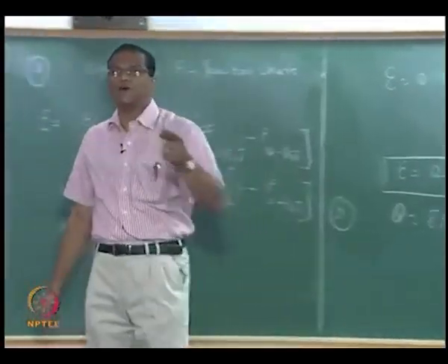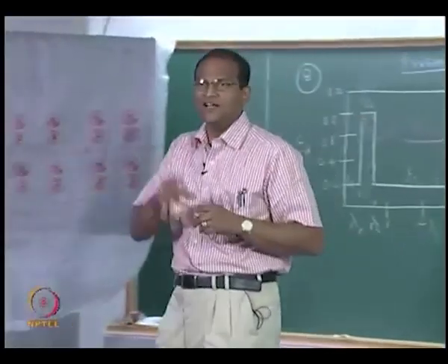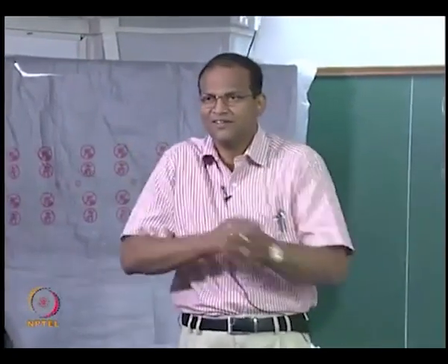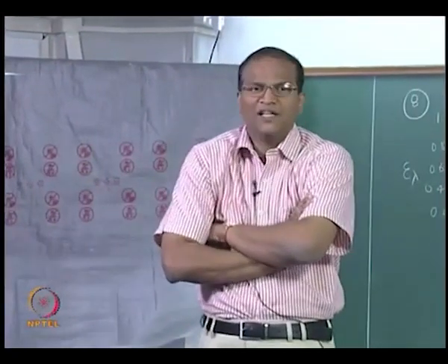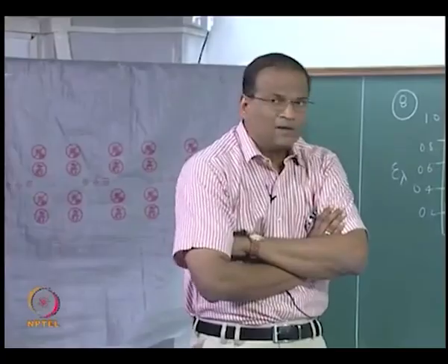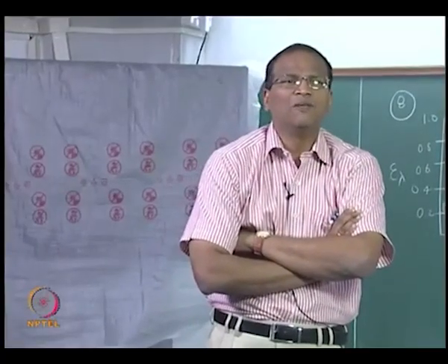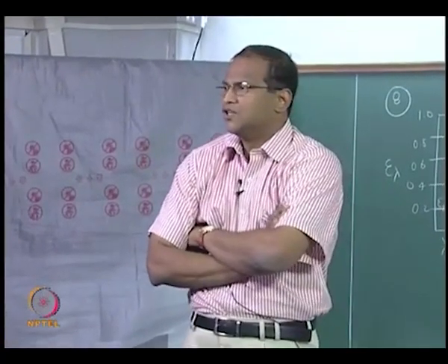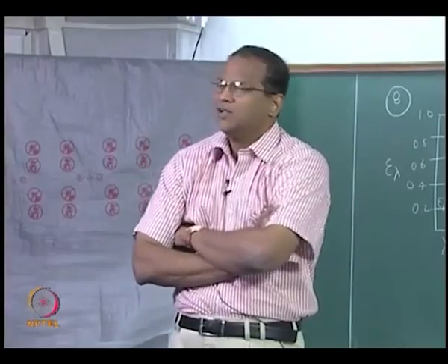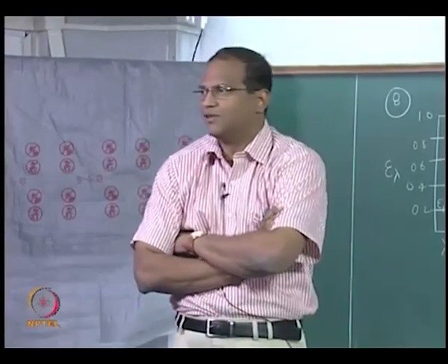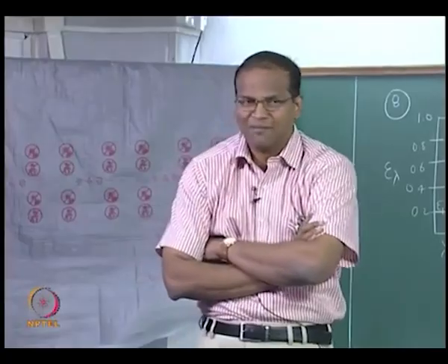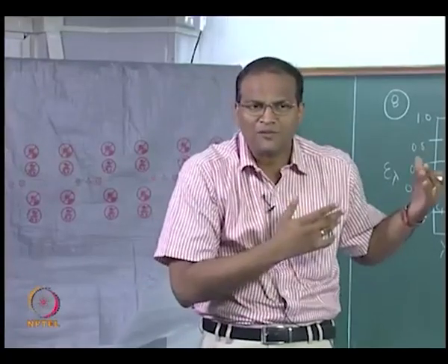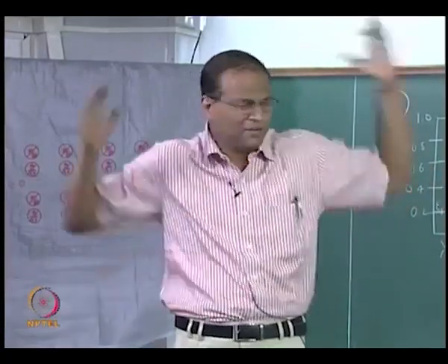So Vikram will again ask me, how are you putting epsilon outside and T infinity inside? You will have to wait for that story. Okay, assuming that that is correct, both the filaments are operating at 3000 Kelvin, assuming that the ambient temperature is same for both, and the Stefan-Boltzmann constant is constant for both the filaments, and the area is also the same. Therefore, the ratio of the power consumption is just the ratio of their emissivities. Fine.